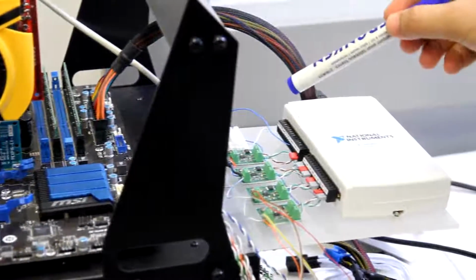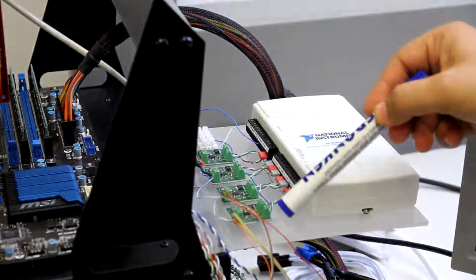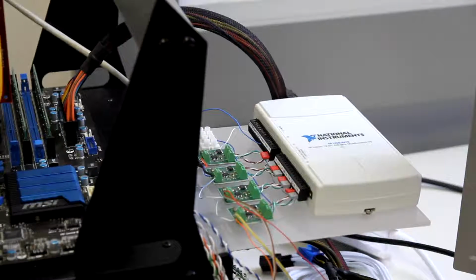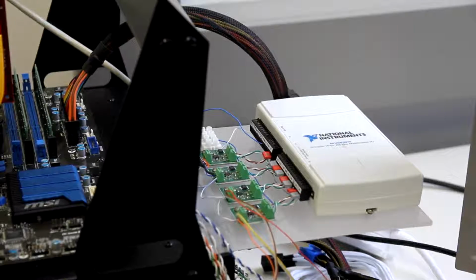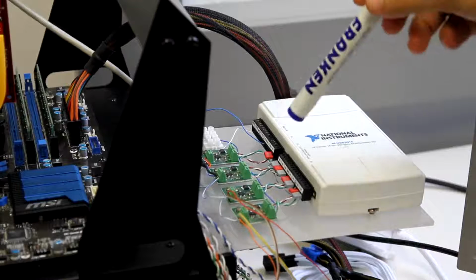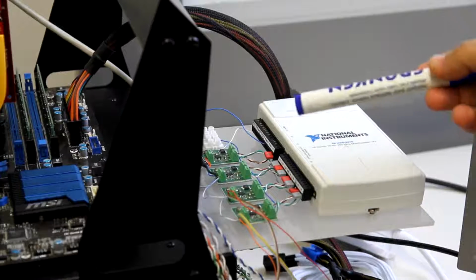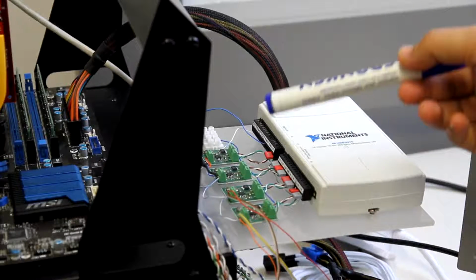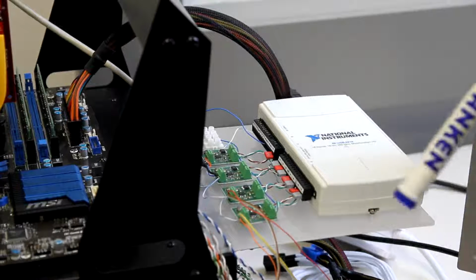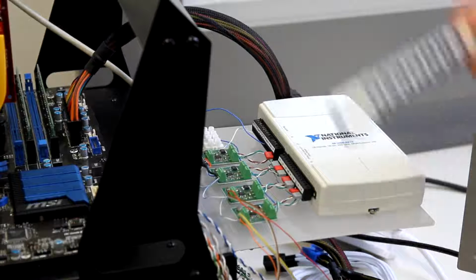Here you can see the 4 signal conditioning boards. So basically the NVIDIA GT240 takes power from only 2 channels, but we have 4 signal conditioning boards because some other boards like the GTX 580 have external connectors also, and our power measurement setup is able to measure power for those cards also.